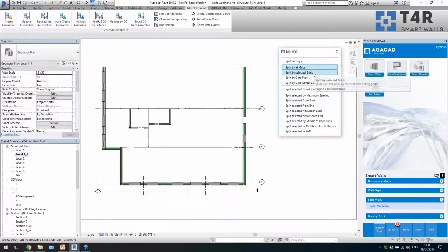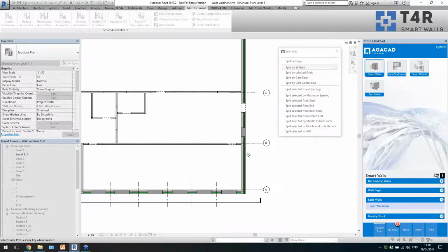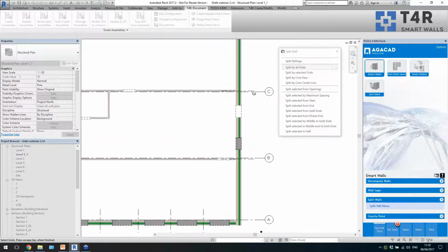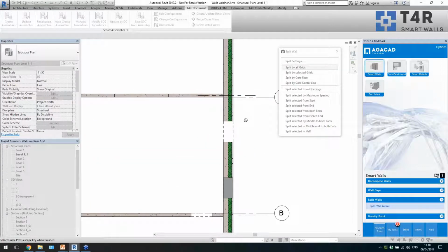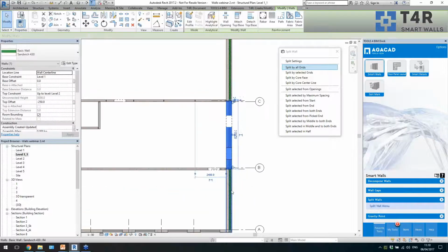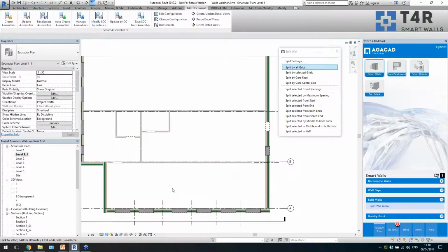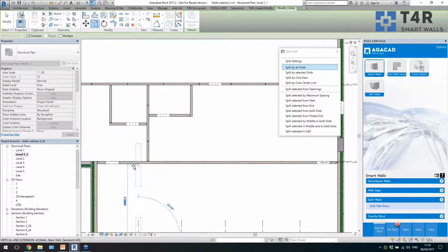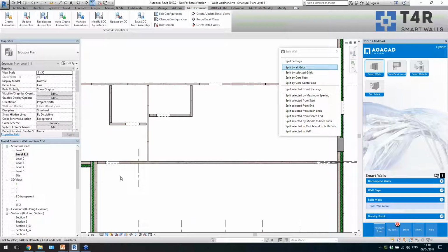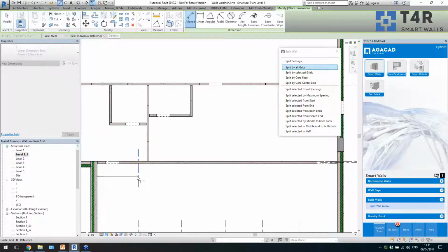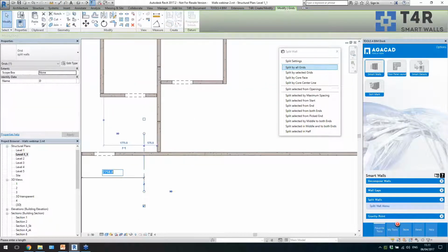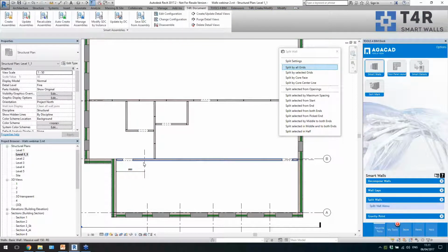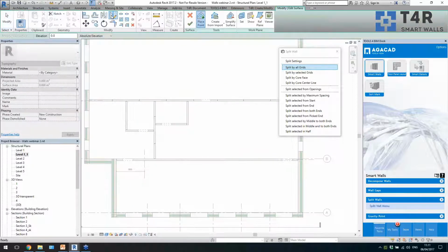Yes, split by selected grid lines. So again, we can just select this one, escape, now select the wall and click OK, and now I will have this kind of panel split, right? So actually I will do the same over here. Let me define the distance. If I want to have an exact distance, I will do it like this, and I will also mirror it. Oh, sorry,